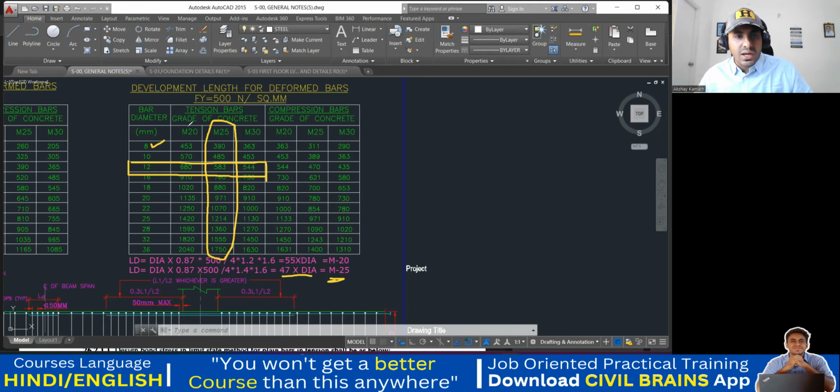For M20, if I want to find the development length for a 12 diameter bar, I should get 680 as my answer. If I do 55 into the diameter, going for 12, 55 into 12 is 660 mm. This is the answer I should get. Here they are getting 680. I don't know from where they are getting the additional 20 mm.